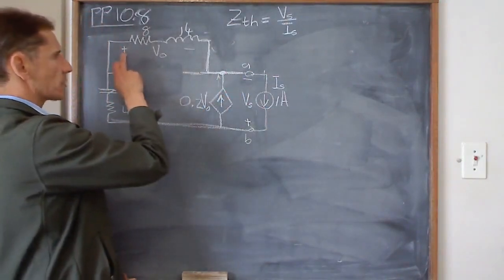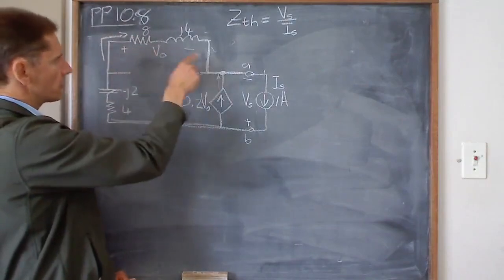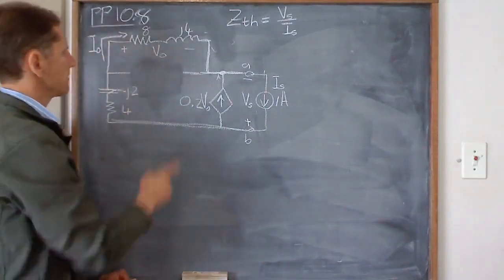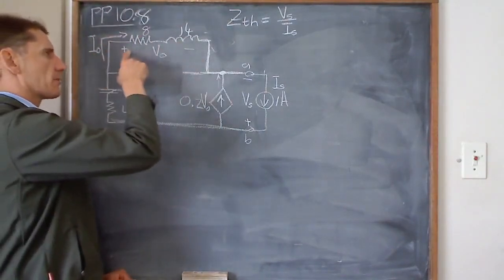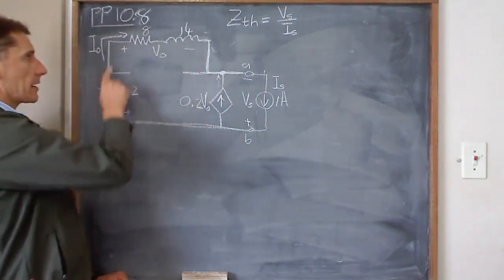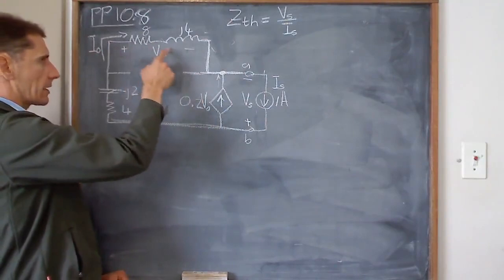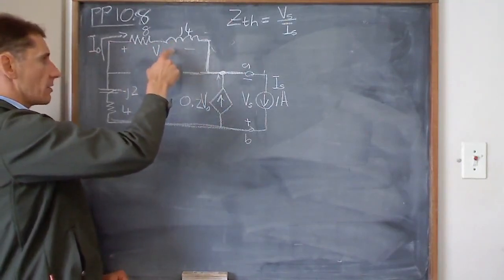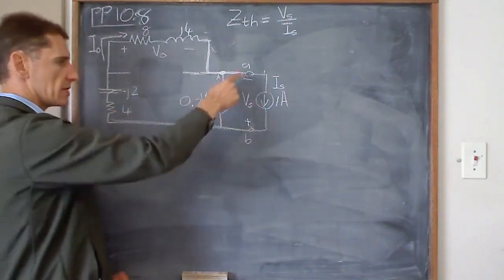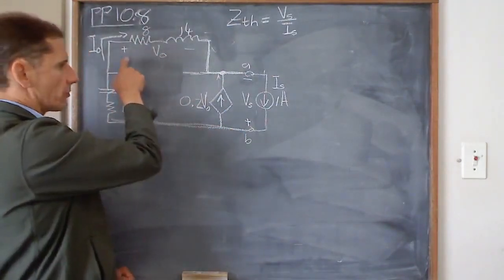Because this one is plus and minus in that direction, let's define a current flowing through that resistor, and we're going to make this I out because it's V out. I'm making it go in this direction because I've got a positive negative. So that current is the current flowing in this whole branch. If I know this current, I can calculate V out, and then I've got the voltage across the total impedance, which is then VS. Okay, so can I solve for I out?